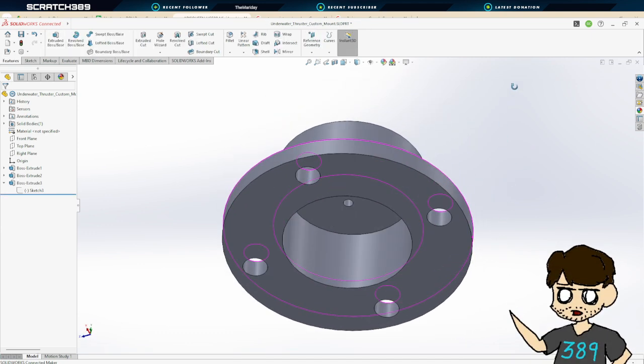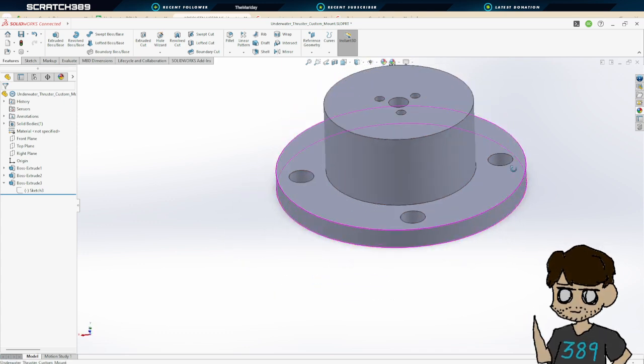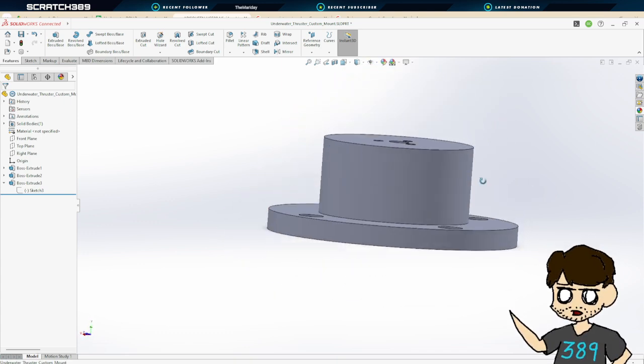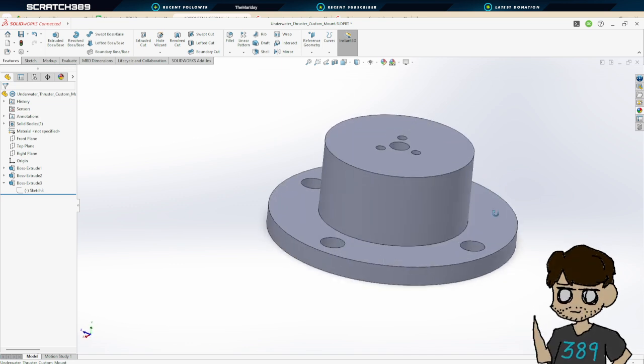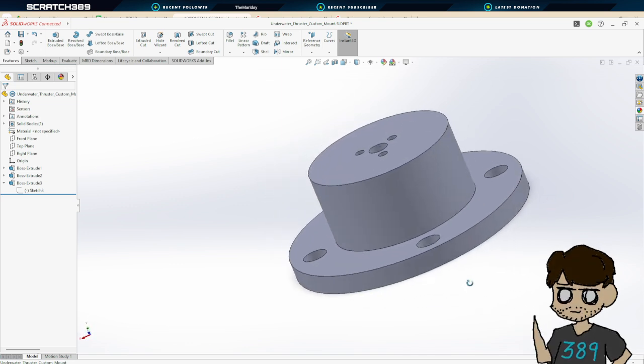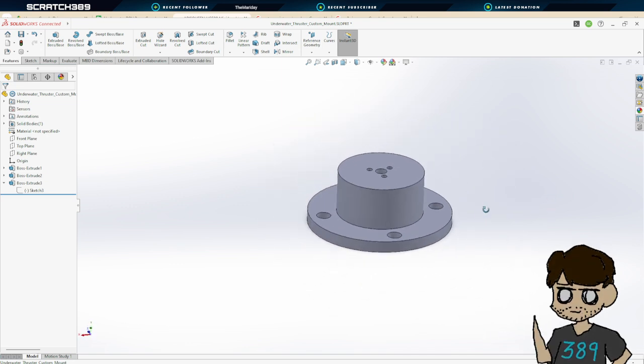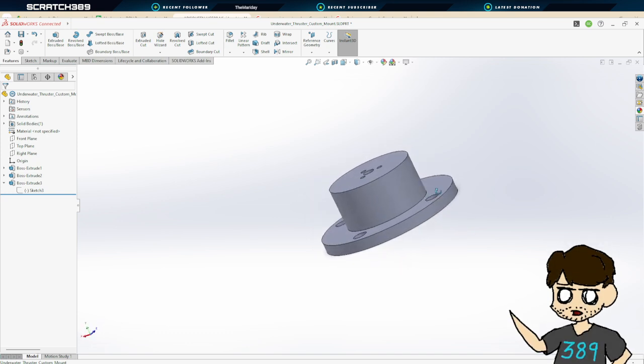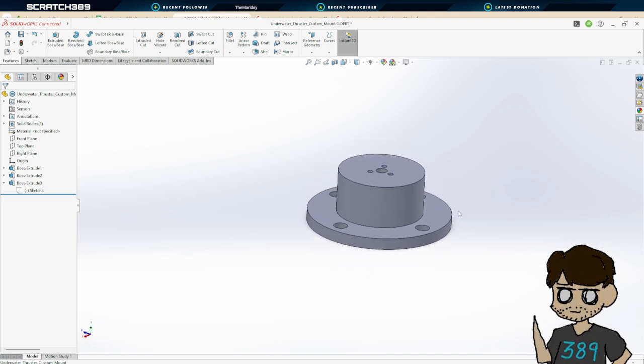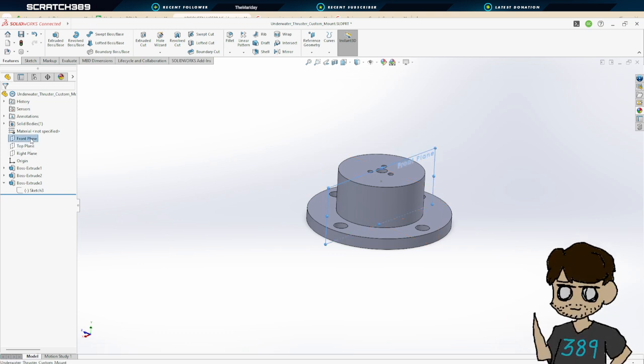This will be the top piece. So the motor will get put into here. Oh, I need to make a slot for the wire, actually. Alright. Where would the wire go? Yeah, okay, so just sort of off to the side. Right plane, top, front plane. Let's do a sketch here.